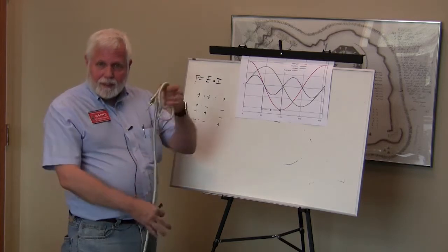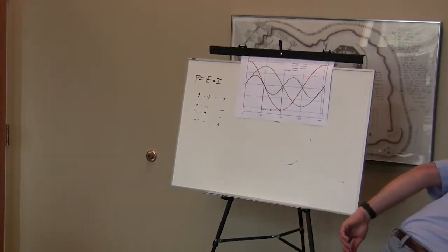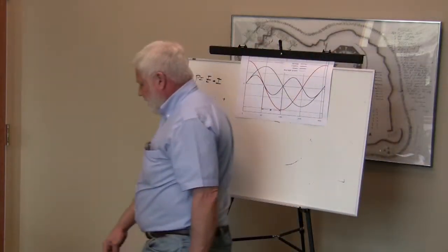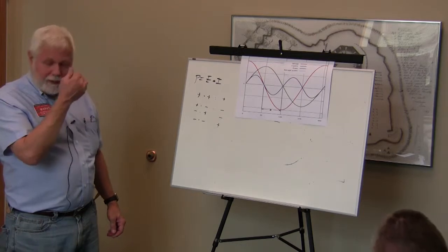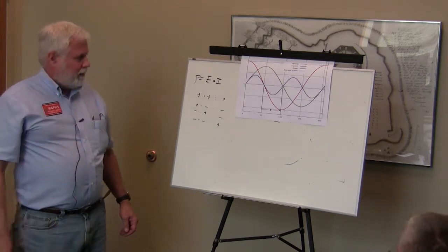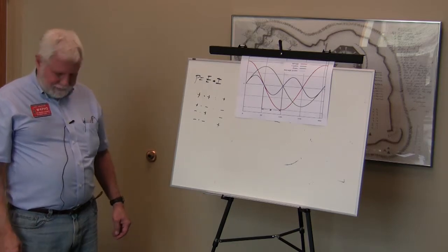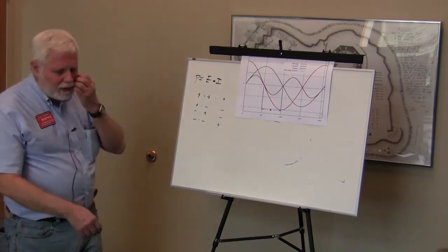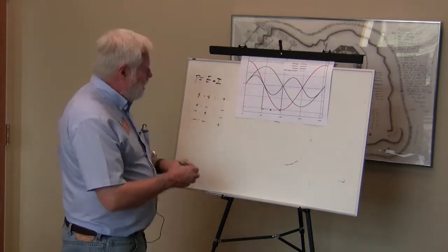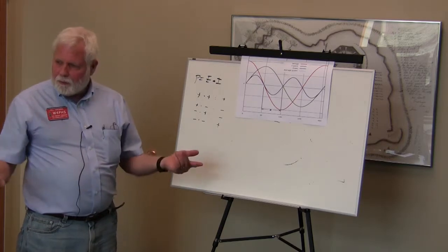Yes. I was just going to say, in a lot of people's minds, they think of power production. Power can be consumed, it can also be produced. In this case, you're talking about power consumption. That's right. So when you have negative power, that means negative consumption, or actually the production of power. That's correct. It's returning power that's stored back into the system. So that is why a capacitor or inductor doesn't dissipate or consume power.